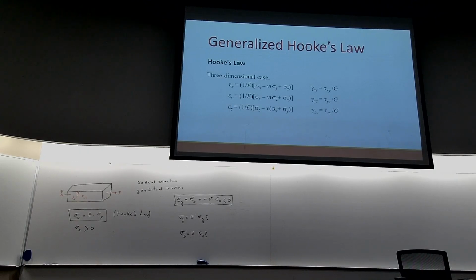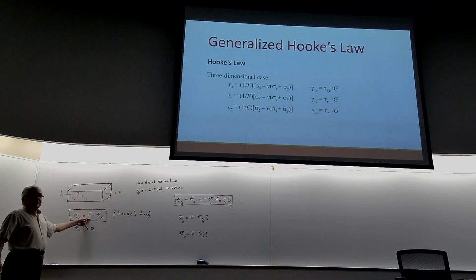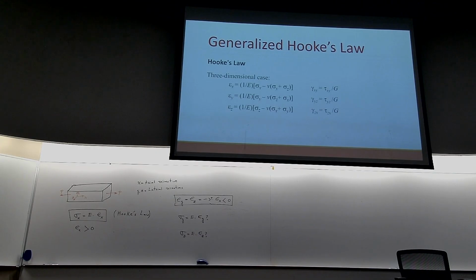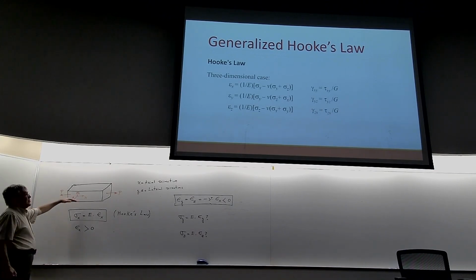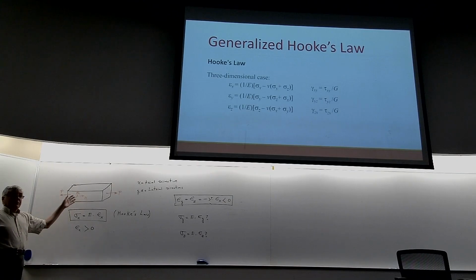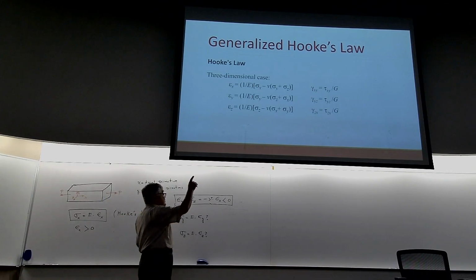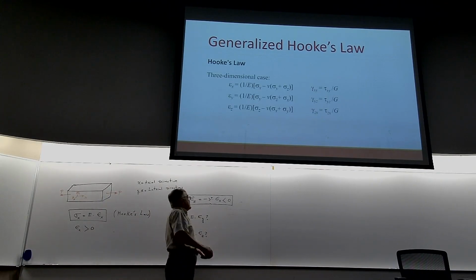That means that Hooke's law in this form is very dangerous because sometimes it works, sometimes it doesn't. That's why we need what's on this slide, generalized Hooke's laws. These equations always work in every problem. You could have forces in one direction, two directions, or all three, and those Hooke's laws, the ones shown on the left side of this slide, always work.